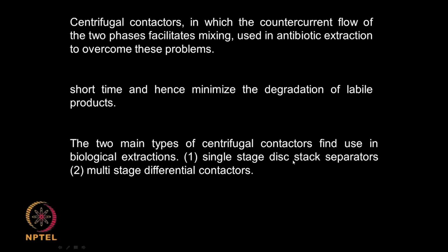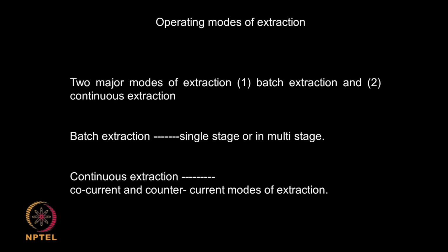You can also have a disc stack type of contactors. I talked about it and showed pictures of the disc stack centrifuge. Similar disc stack systems can be used for liquid extraction also, or you can have multi-stage differential contactors. So, you can have several contactors in many stages. Centrifugal contactors are becoming quite popular if you are interested in short contact time, very high mass transfer and very high dispersion of these two liquids when compared to the traditional tower or the normal mixer settler type of contactors.